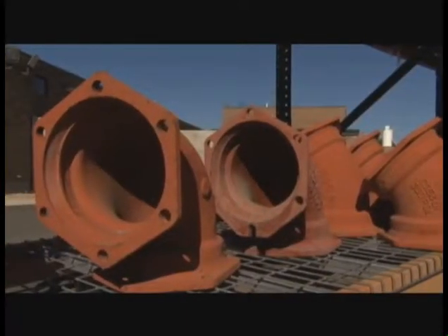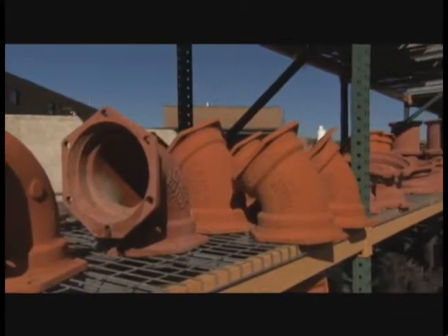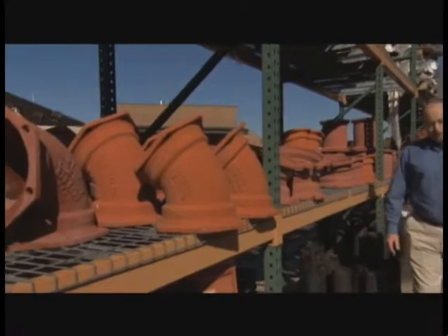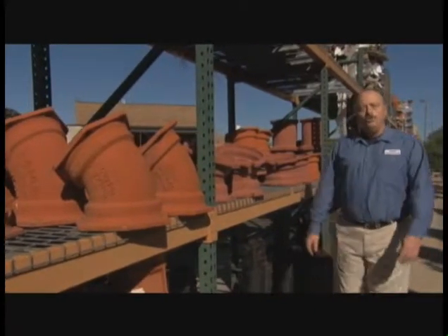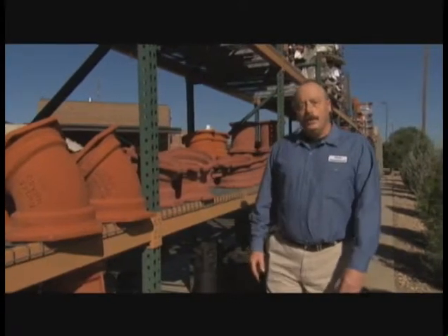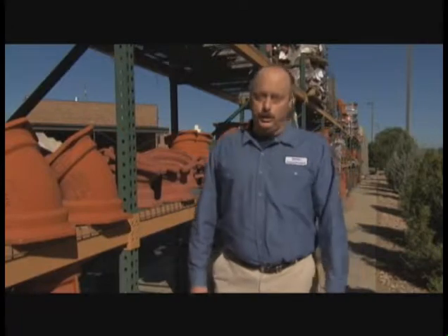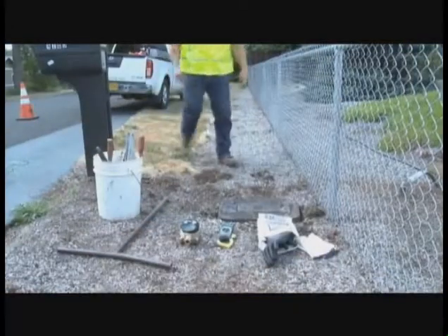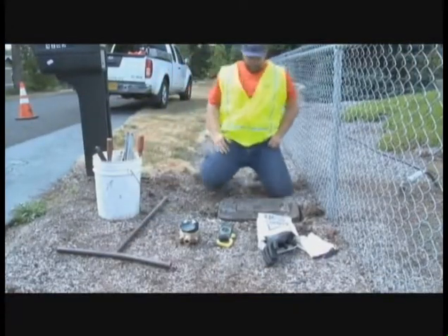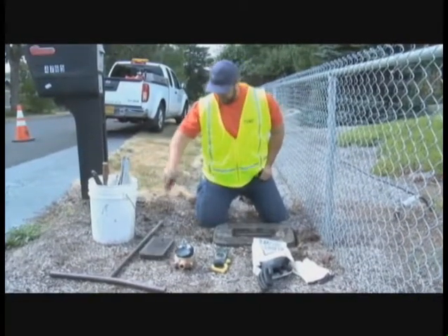Electric shock is a danger water utility workers face during the installation and service repair of water pipes and meters. Water pipes are often used to ground electricity in homes. If there's a fault in the electric system, the pipe and distribution component can be energized with electricity. A severe or even fatal shock can occur if enough electricity is present in the pipe or meter.